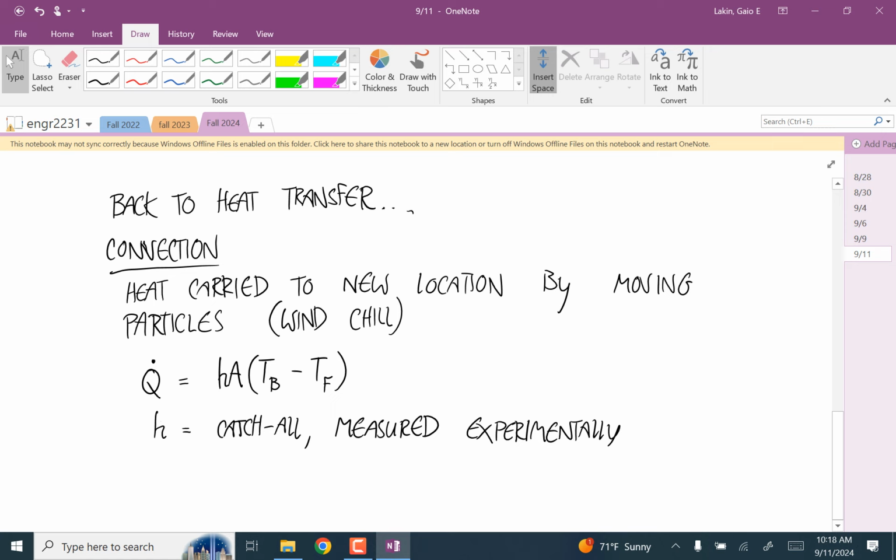It has to do with how fast the fluid's going, though, in addition to how readily the fluid takes up heat. There's no table that I'm aware of. If you know that you want to use this equation in a certain setting, you'd have to do some experiments to figure out what this H is in your case, and then you can use it for calculations. This is the one that I don't think there's any way to just Google. You have to make sure it's with the same stuff you're using. Right, exactly.